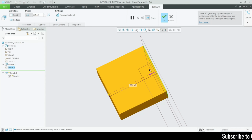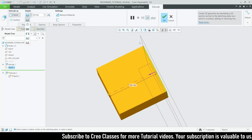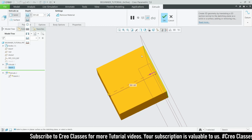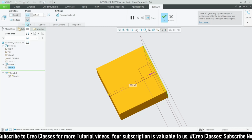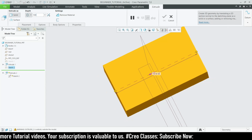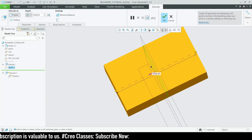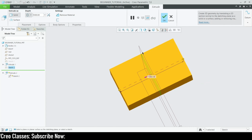If we need the part to be extruded on both sides, you can see the depth option here. You can select this symmetric option. It will be extruded symmetrically on both sides of the sketch plane. This plane is nothing but a sketch plane. If you need to extrude on both sides, click on this and it will be our symmetric extrude. If you add a value of 1000 here, from this plane to this end it will be 500, and from this plane to this end it will be 500. So this is how it will be split.